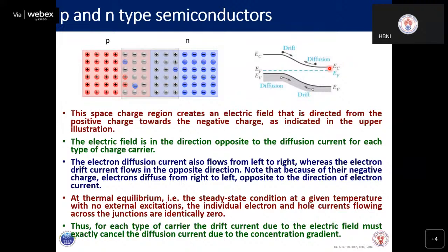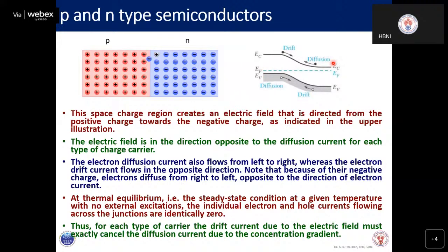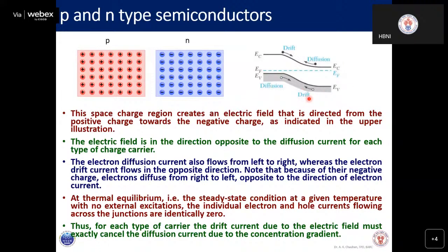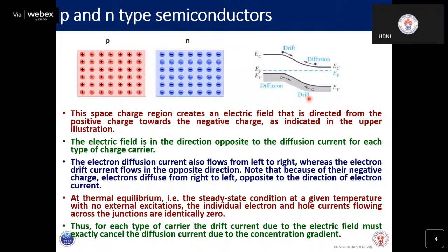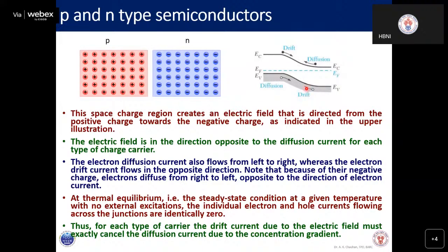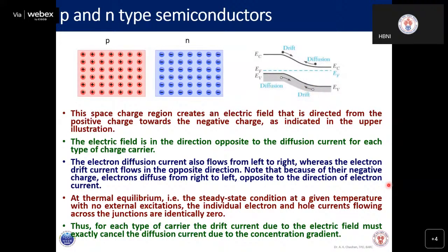It depends on the Fermi level difference between N type and P type, and it is material specific. Normally, if you are not changing the composition of your material, the built-in potential will be constant. You should understand this process because solar cells also work on this principle, and junction diodes also, where we utilize these properties.